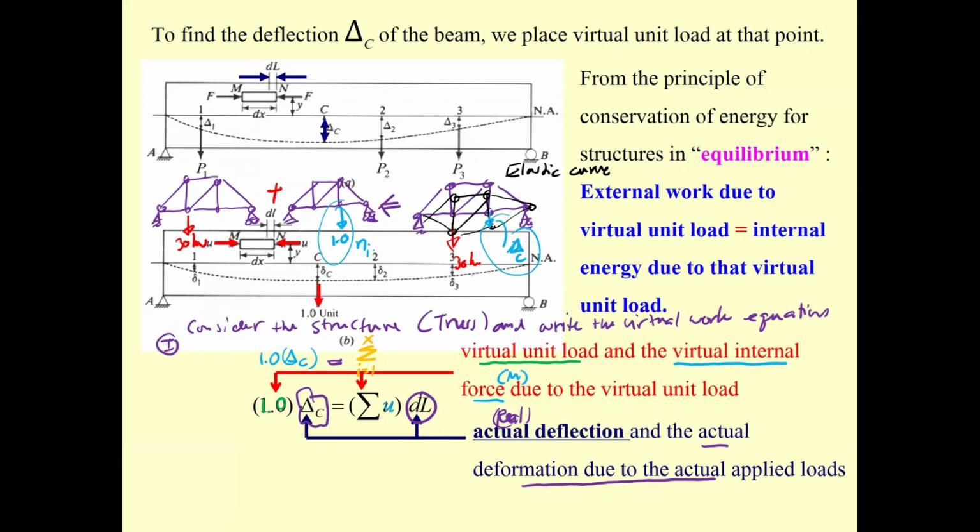I call this one small n sub i, so that is the force n sub i, times the force for the real structure, capital N sub i, and then L sub i over A sub i E sub i.